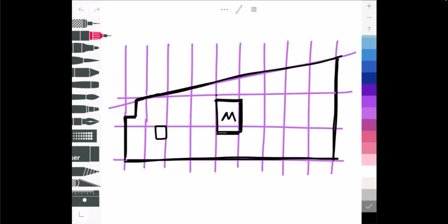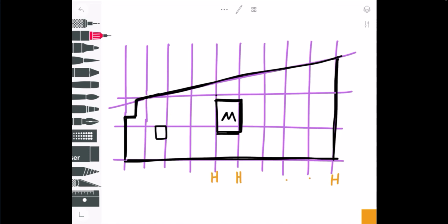So again, I'm just going to look at this quickly and say, okay, I've got a high point here and then low, high, low, high. I think that works out pretty good knowing my mechanical penthouse is there. And if I work my way along here, if I said that's high, I'll get to why I'm doing that in a minute. High, low, high, low, high. That works out pretty good. Got a high point on the perimeter. And for this one here, we could say high, low. I would probably do low again and high so that I get a high point on the perimeter again right there.